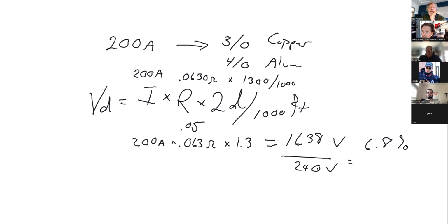Whatever wire they're bringing in from the grid to your service panel there at the pole is probably acceptable. You'll have to check with the utility, because how far can you run using that wire before you have enough voltage loss that it's a problem? That's what you gotta find out.